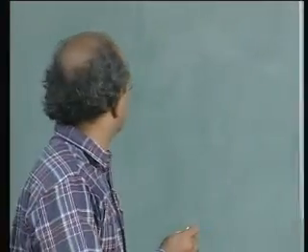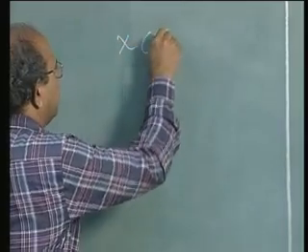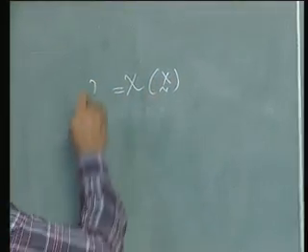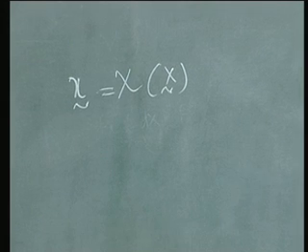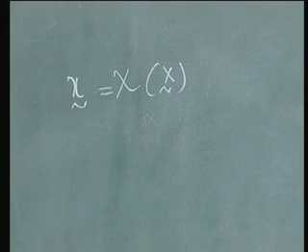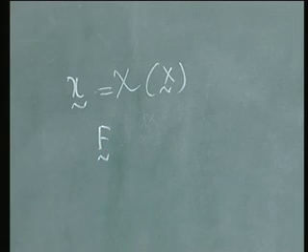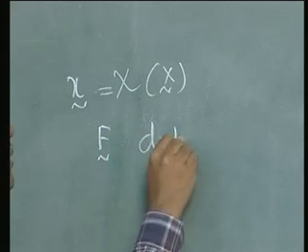In the last class we started our study on continuum mechanics, and we had defined what we called deformation to be a mapping function. Then we defined one of the most important quantities in continuum mechanics, which we called F, and which we named the deformation gradient.